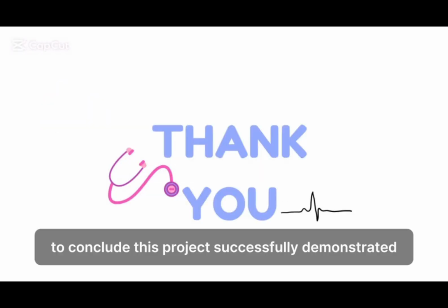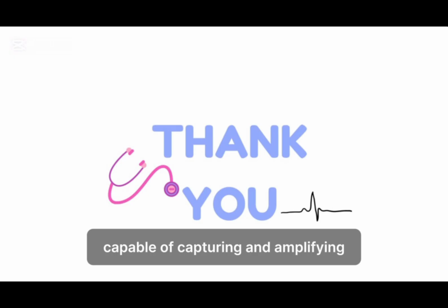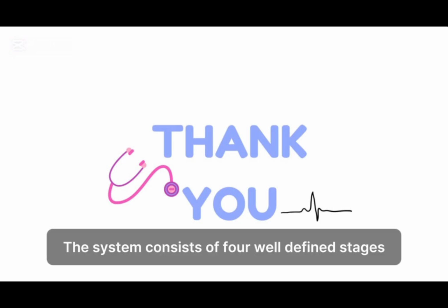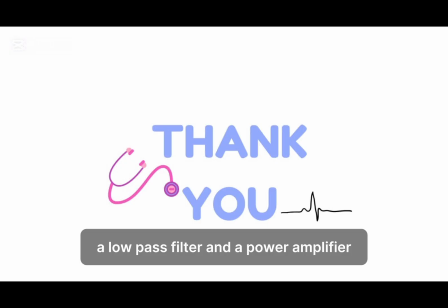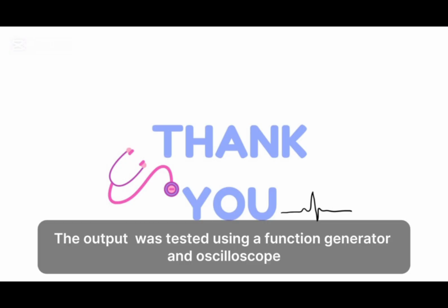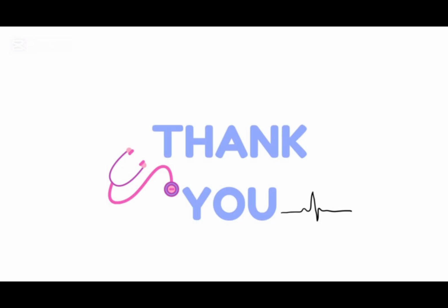To conclude, this project successfully demonstrated a complete biomedical signal processing circuit capable of capturing and amplifying a heartbeat signal from a stethoscope. The system consists of 4 well-defined stages: a preamplifier, an adjustable gain amplifier, a low-pass filter, and a power amplifier. The output was tested using a function generator and oscilloscope, and the measured gain and frequency response match theoretical expectations.